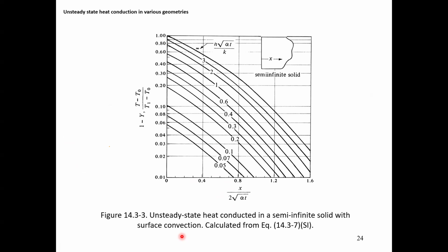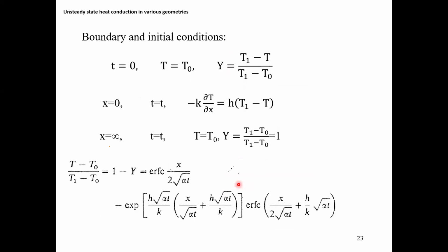In undergraduate classes, for different geometries, we would be using different plots such as this to calculate the temperature T for different times t or at any location x. Within this analytical solution you have C, which is 1 minus the error function. You can google it and see what an error function looks like.